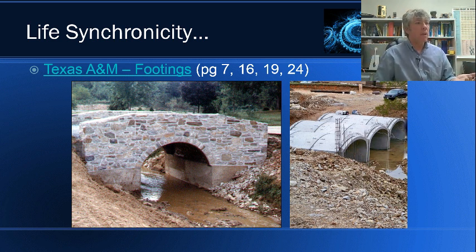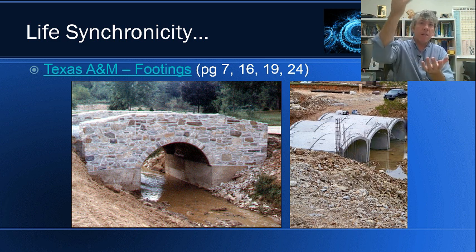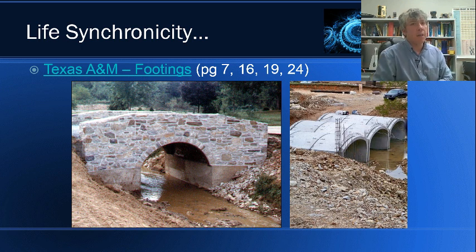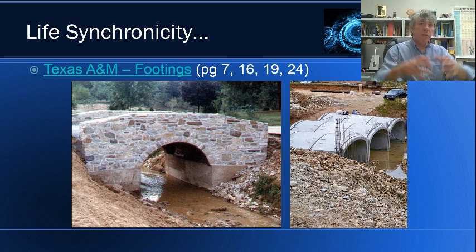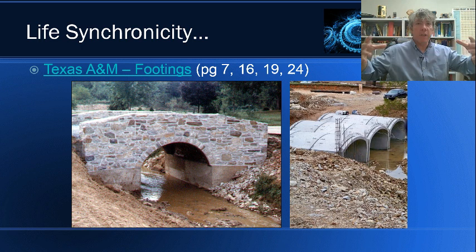So how do you put a material on top of that that is supposed to then take a force and distribute that force over an area, so make it a contact or bearing stress? How do you do that well? And this reference gives some information on how much stress various soils can support, so that way you can decide how big your footing needs to be.